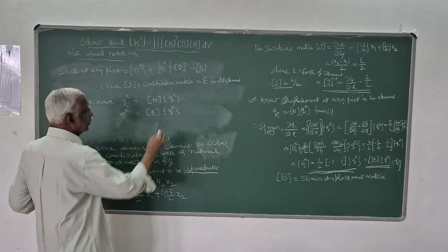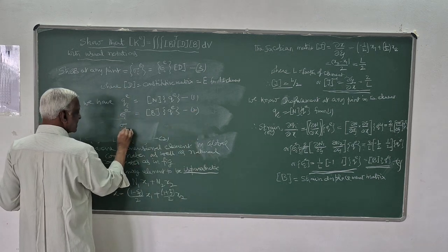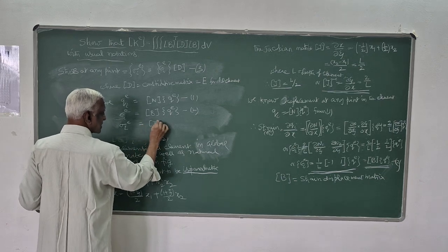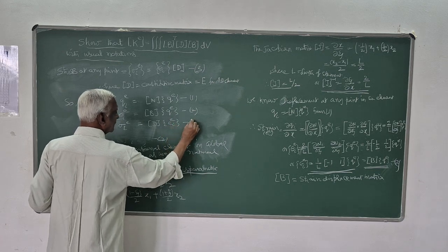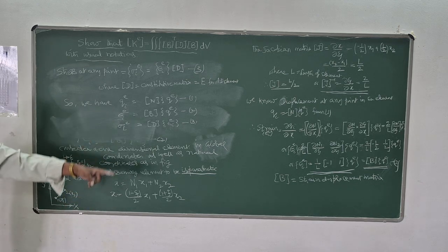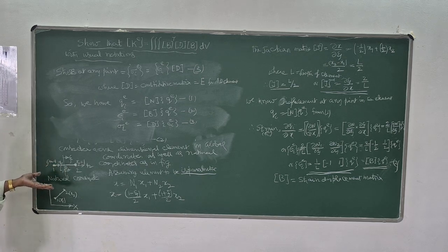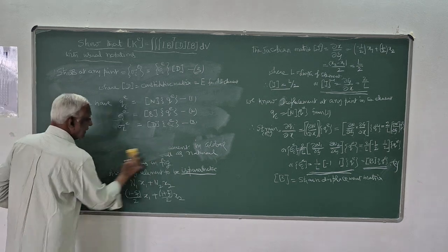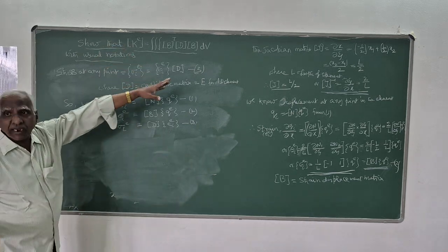That is relationship 2, this is relationship 1. Then sigma I, stress, is given by the constitutive matrix into strain. This is the third relationship. So I have just shown that for an isoparametric element, treating the isoparametric element concept as the basis, I have these 3 relationships. Because in the derivation they have asked for usual notation.